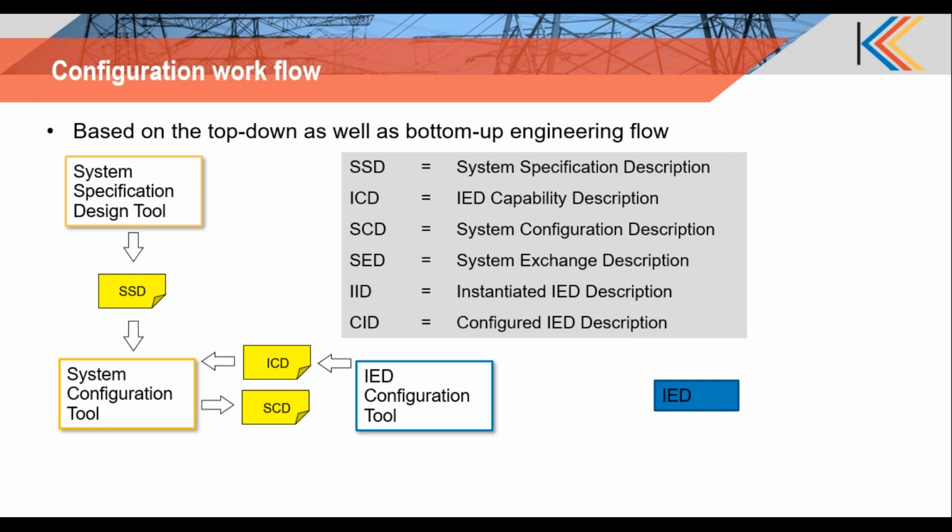Now, once the SCD is generated, it acts as a master file, and it's possible to use multiple IED configuration tools. Given that in a particular project you may have IEDs provided by multiple vendors, you can load the same SCD file into these multiple tools, and the tools will extract the configuration required for each device connected to that tool. It will extract that information, and that will be downloaded into the IED. So this is the general configuration workflow.